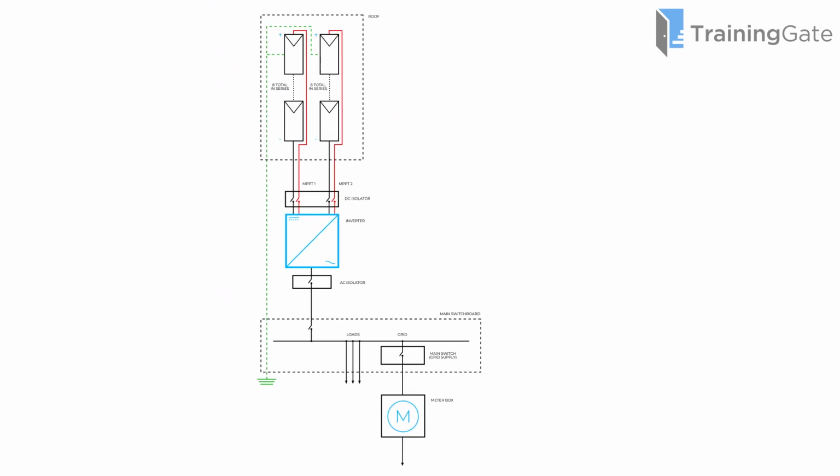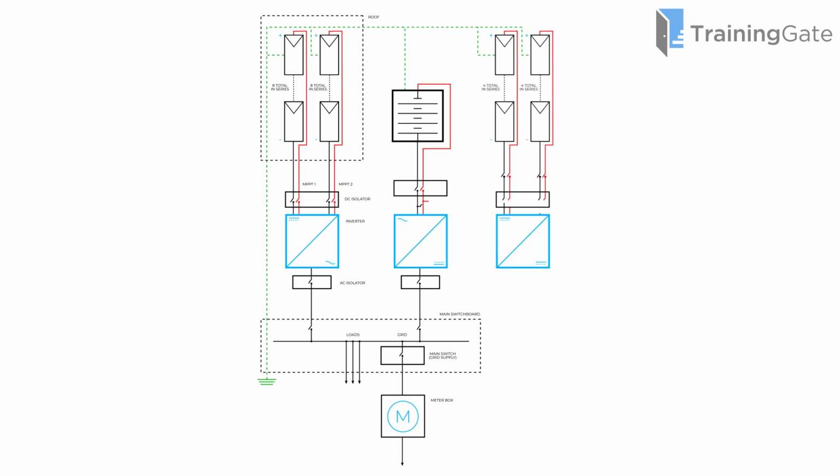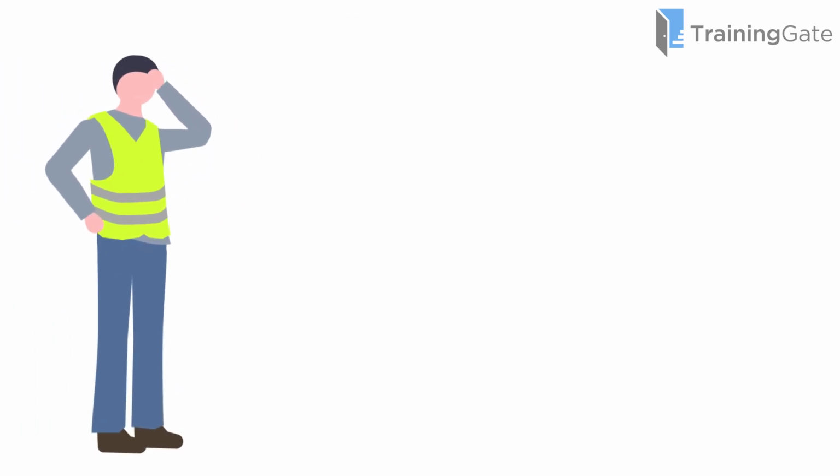SLDs use standardized schematic symbols. It's important to become familiar with these so that key system components can be identified at a glance. The orientation, size, or line width of a symbol does not change its meaning, though it may be adjusted for clarity or emphasis. Where needed, dash-dotted boxes can group symbols to show that they belong to the same physical unit or location, such as an integrated inverter battery system with integrated isolators, or the PV array and disconnectors being located on a roof.